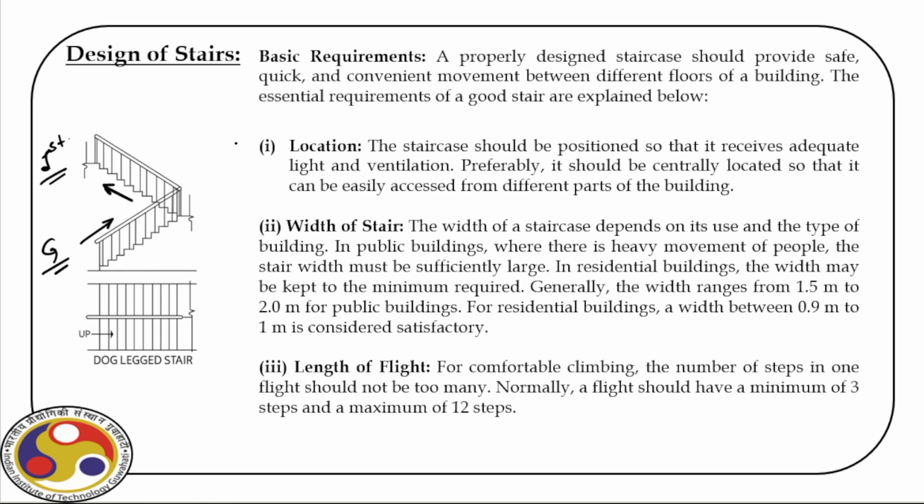Now, the width of a staircase is extremely important because that provides safe passage from one level to another level, right? So, depending upon the type of structures that we are going to design, this width may vary. For public buildings, obviously, we should provide space for heavy movement and therefore those stairs are wide compared to residential buildings.